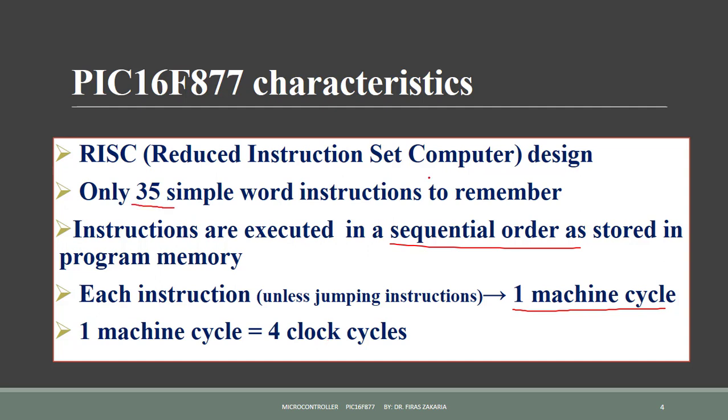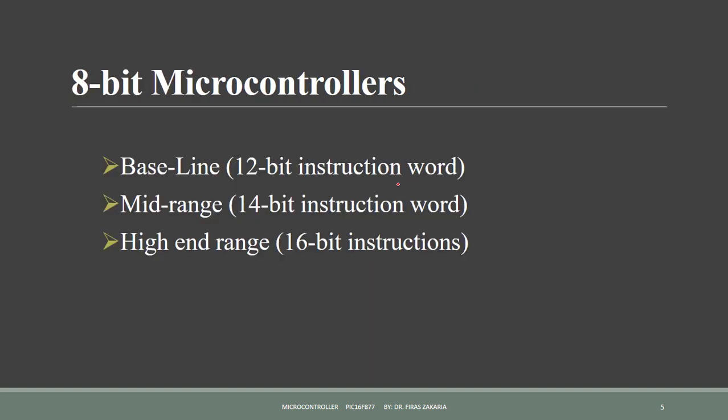So the instructions are usually programmed into the flash memory of the processor and automatically executed by the microcontroller on startup. In general, the architecture of the 8-bit PIC microcontrollers can be categorized as mid-range family that uses 14-bit instruction word. It offers a 14-bit instruction set.